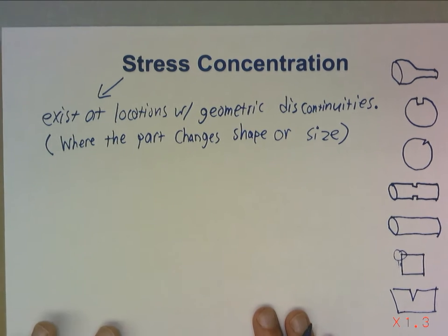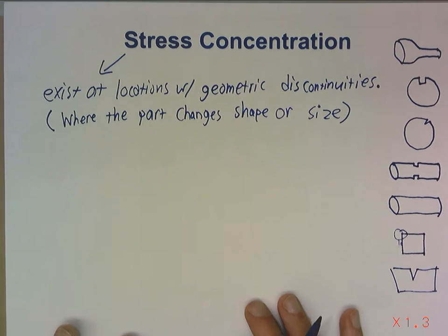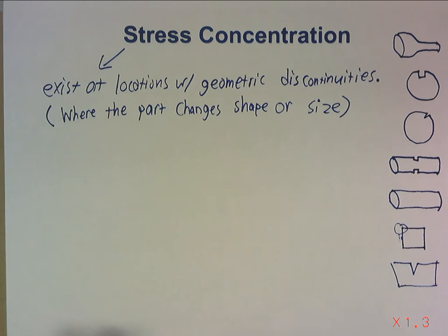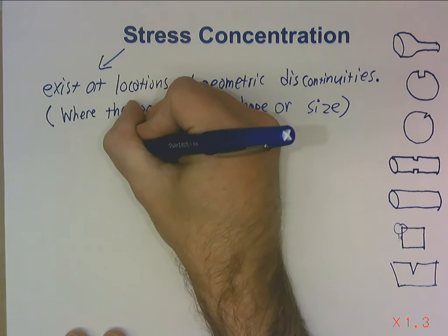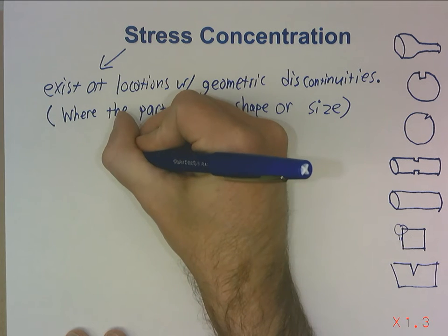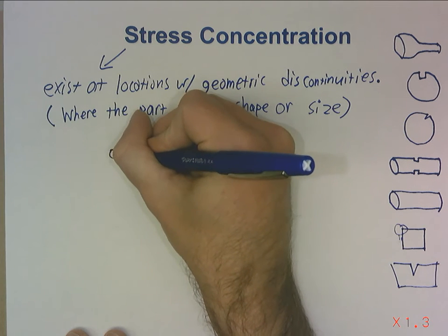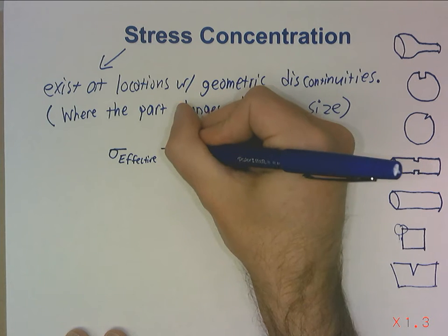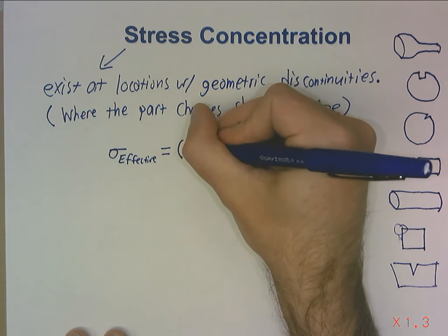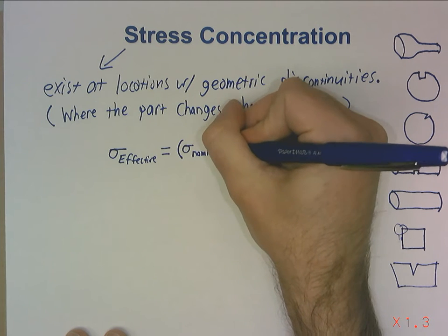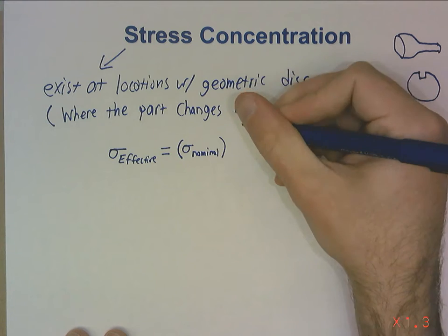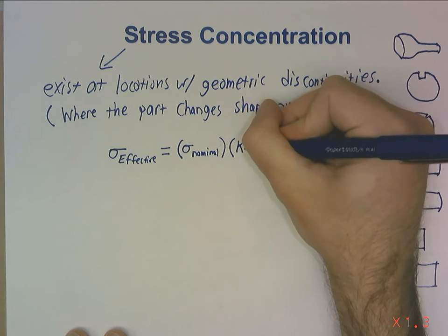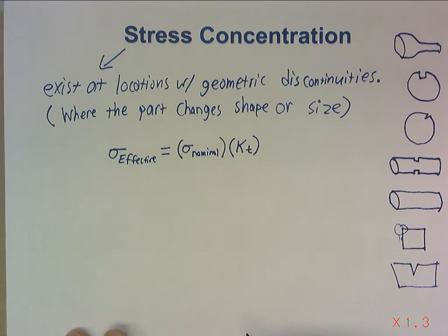there will be an equation that, at least for a first take on stress concentrations, is very straightforward. Our effective stress equals a nominal stress times some factor.